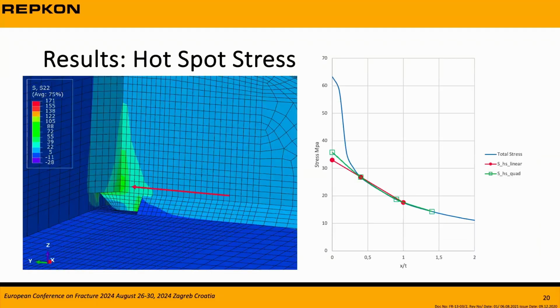Hotspot stress results, and in this graph, stress in megapascal and X over T results, which are total stress, linear extrapolation, and quadratic extrapolation for the path given here.